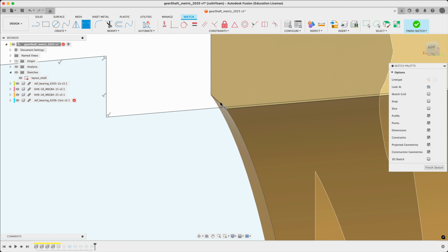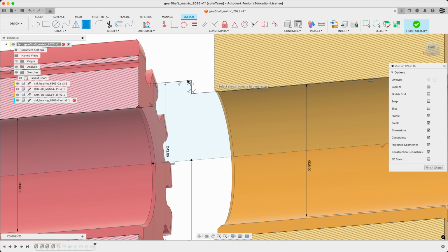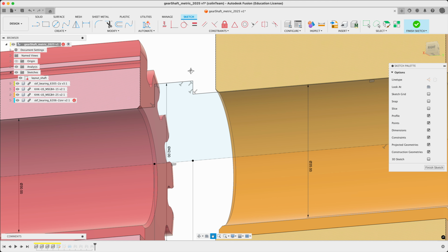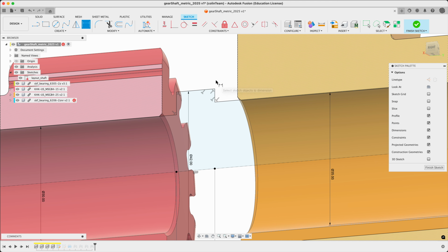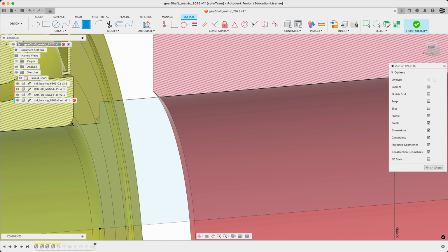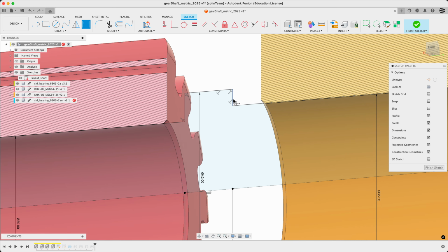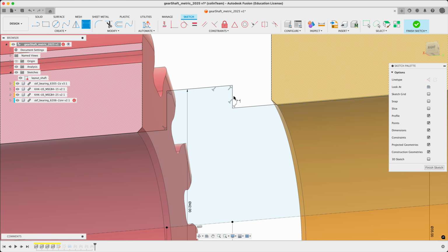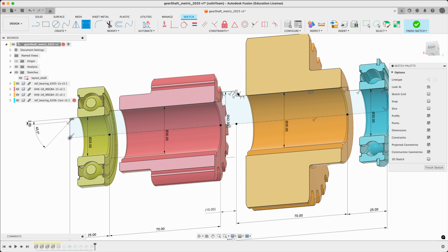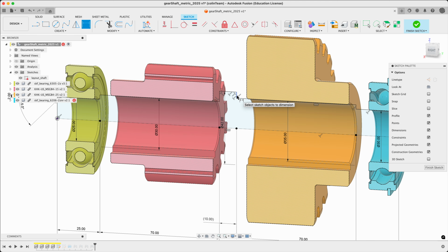See, this gear actually has a very small chamfer. Both of them are from KHK. So we actually are going to end up with probably a sharp fillet on everything here. We won't be able to fit a well-rounded under this. So we have quite a tight fillet coming. So this is not too bad, actually. We could probably get away with this. We'll see how it goes.